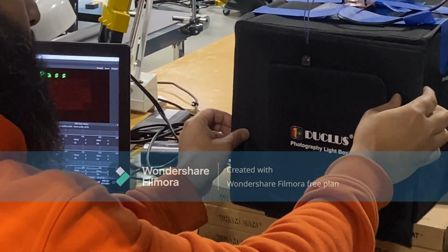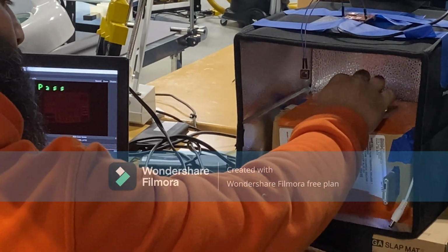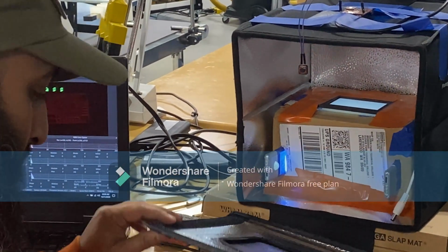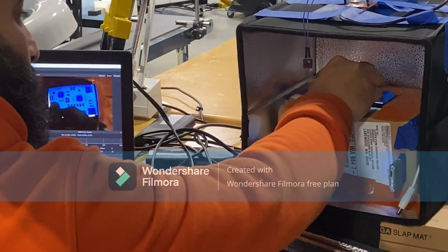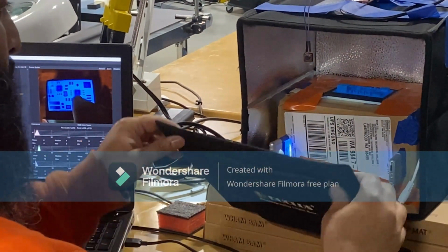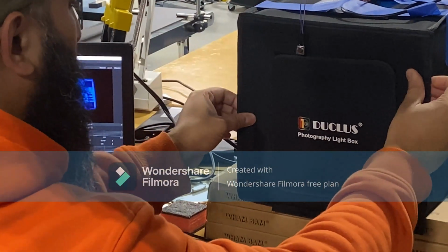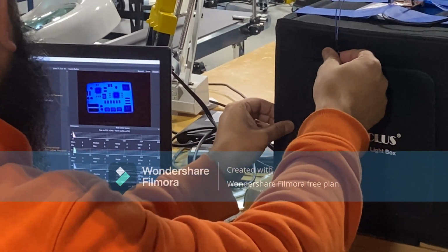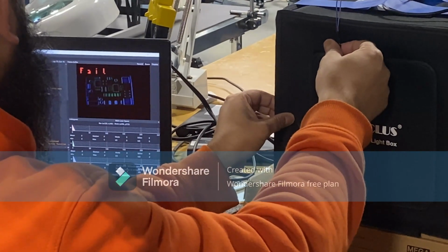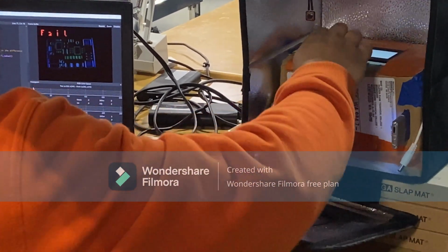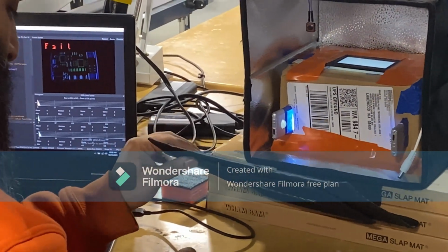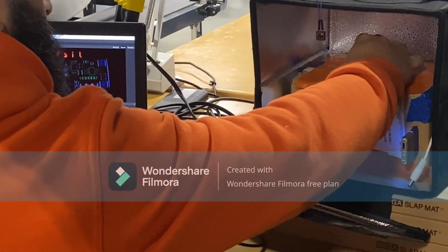The camera system used for this application was the OpenMV H7 with a QVGA 320 by 240 pixel resolution to capture the image. The maximum part size was 2 inches in height by 3 inches in width, which made the distance for the field of view need to be at least 5 inches from the camera and possess a 72-degree field of view to capture the entire circuit board.